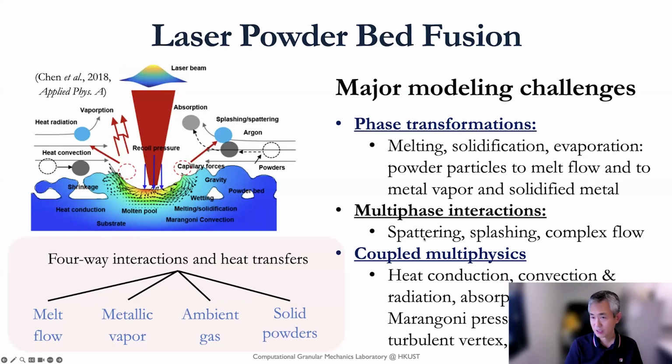And also it's a multi-phase interaction. Apparently you have a solid particle, and then you have spattering and splashing complex flow, and a vapor flow, gas flow, as well as this liquid flow, right? And also the physics is complicated. It involves heat conduction, convection, radiation, absorption, and we need to consider recoil pressure, Marangoni pressure, flow drag, turbulent vortex, and also capillary force. So they summarize all the challenges we need to consider in such a simulation.